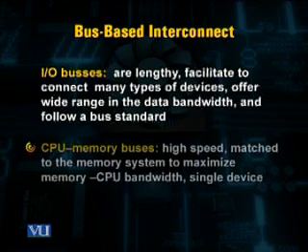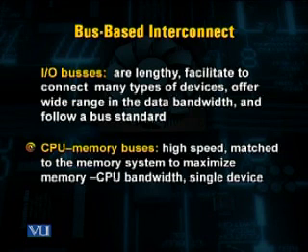Whereas the CPU memory bus, which is also sometimes called the backplane bus, is in fact a high-speed bus which matches the memory system to maximize the memory CPU bandwidth, and usually it is used to connect single devices.